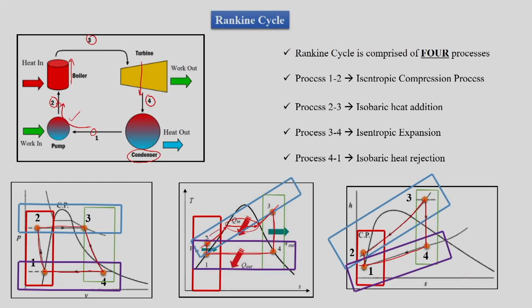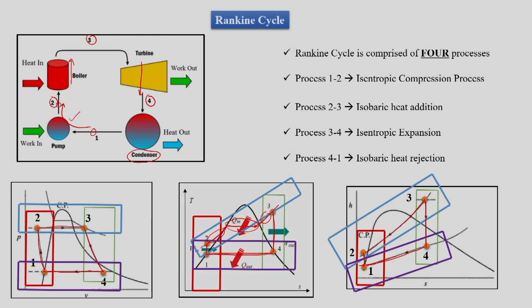But before that, we have supply of sensible heat, where we do not have a horizontal line in the TS diagram. But heat rejection is completely latent heat in the case of the condenser, so it is a complete horizontal line. But when we see the HS diagram, it has a slope which is different from the TS diagram.